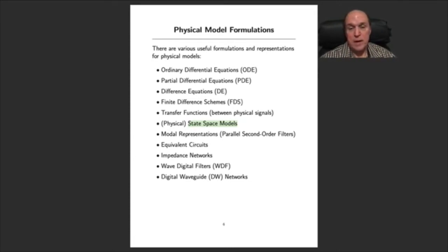model. But that doesn't normally happen without some good optimization going on, because your state space matrices are order n squared, where n is the order of your system, whereas your transfer functions have a set of coefficients of order n. So you have to be careful to not spend more time doing the computation. But what people very often do to guarantee that that's not a problem is that they diagonalize the system.